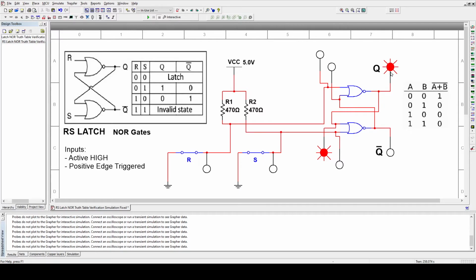Now, I was getting very frustrated with Multisim because as soon as I labeled that as Q, the whole thing just wouldn't work. For whatever reason, it's probably some sort of software glitch. So when you bring up the probes, let them be labeled as they are, and then you can play with the labeling. Now this Q here, I just put it as a text. So you can go place text.